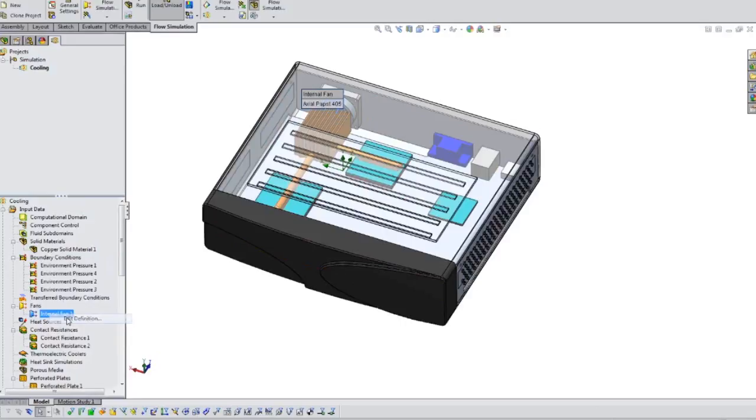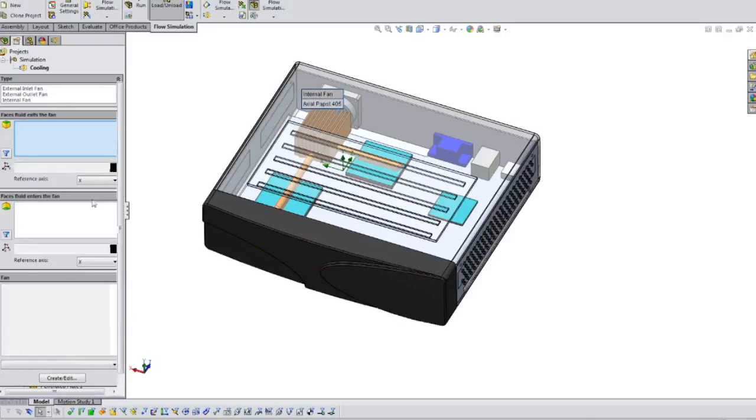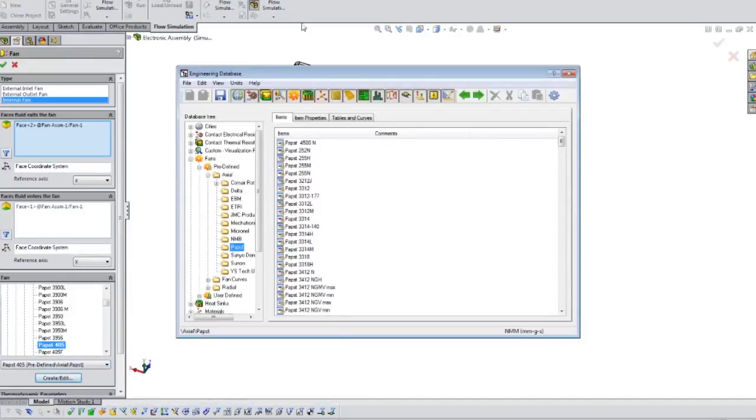And we also want to do things like understanding how our heat transfer tools are working. Whether we're using passive cooling or active cooling, we want to make sure that fans are in the right spot, that vents are in the right spot, that we have enough holes inside of our vents to be able to handle the heat that's actually happening in the model. Again, if you're doing this with a physical prototype, it's a guess and check method. Start with some locations, then if it doesn't work, maybe we cover it up with cardboard and move it over a little bit. I've seen a lot of that in the physical testing that I've seen and worked with customers on before.